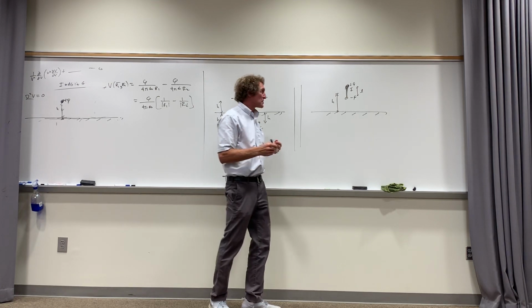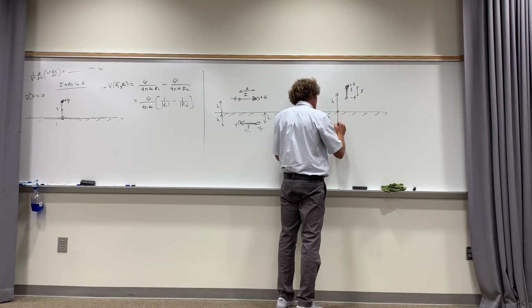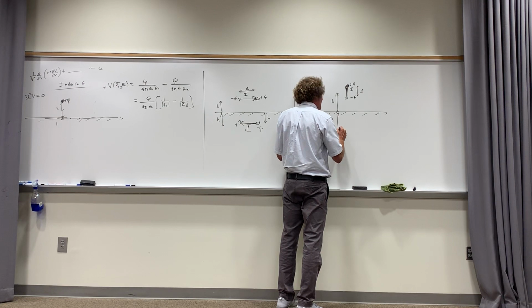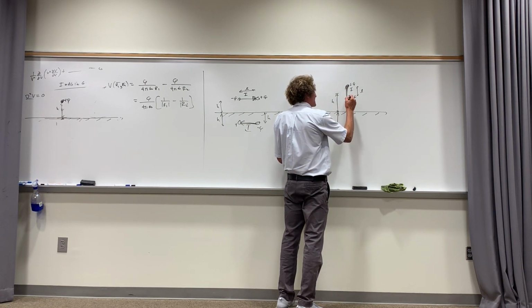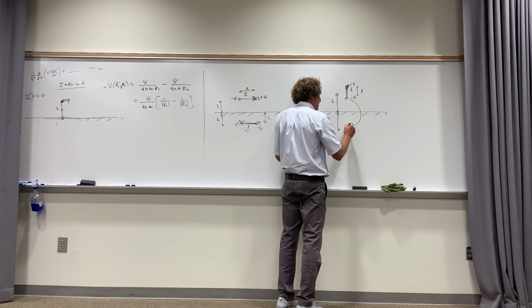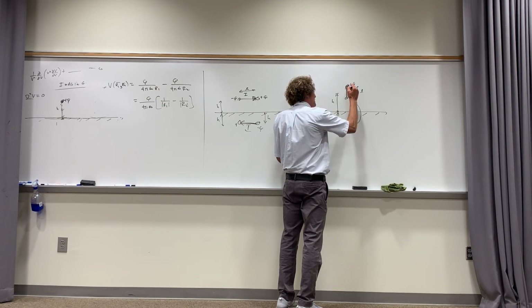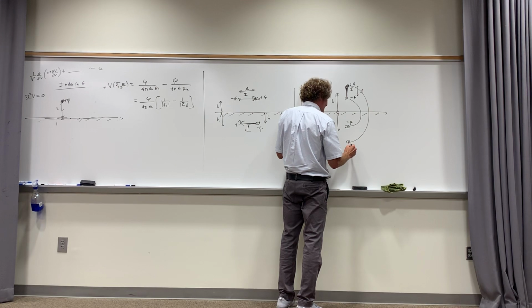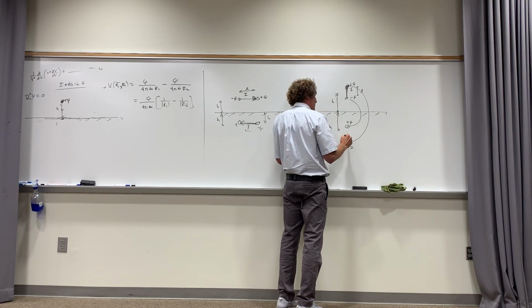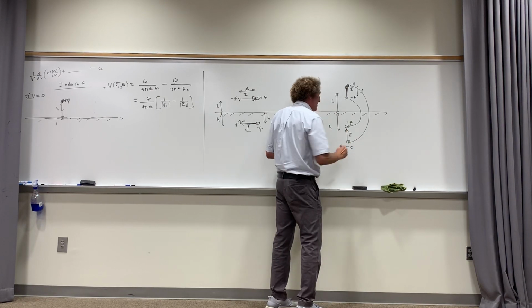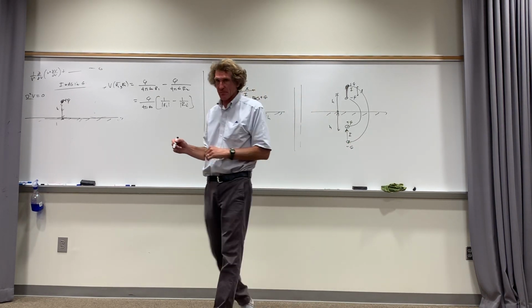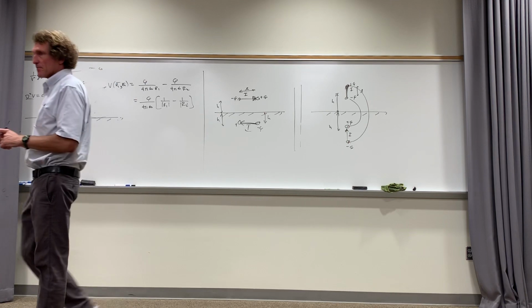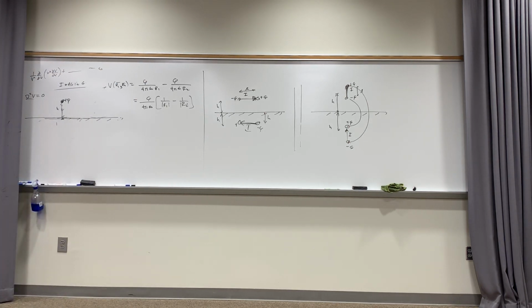All right, now how does it image? Well, if I come down a depth H, right, I would say what? This negative charge would image a positive charge here, and this positive charge would image a negative charge here. And what current would cause that? That would be a current flowing in the vertical direction. And that would be the image. Does that make sense to everybody? Take a look for a second, make sure you see it. You all see it or not?